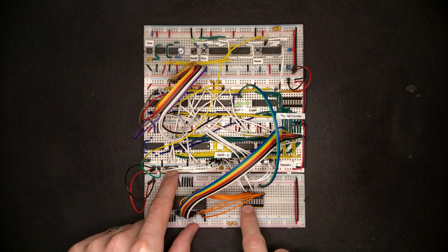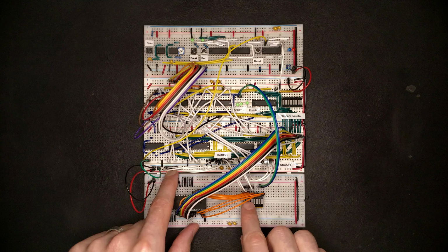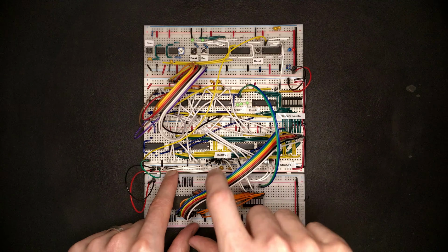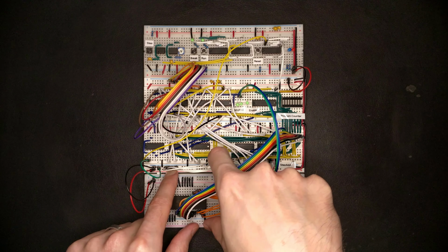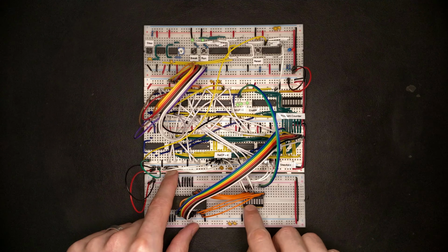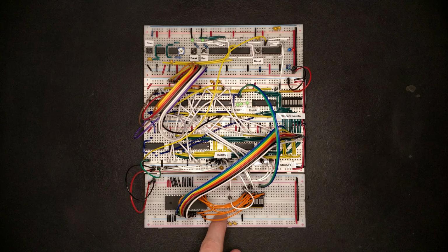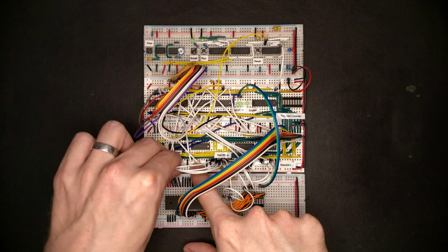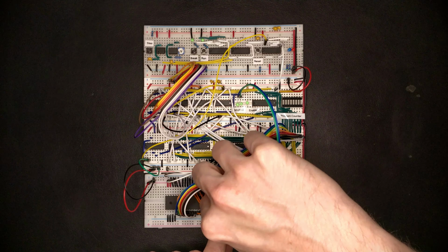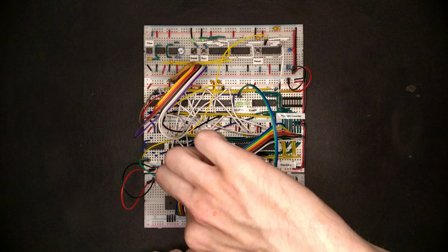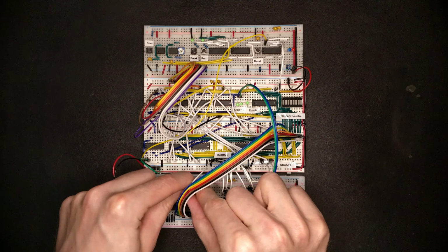So when we interpret these 4 upper bits as a signed number, meaning that when the topmost bit is set, this represents a negative number, this will carry over into the 8-bit relative offset, and the signed number will properly be sign extended such that the number that we put on the 8-bit bus corresponds to the same negative number as we've had here. So bit 4 of the relative jump address will be connected to the topmost bit in memory. And the same for bit 5, bit 6 and bit 7.